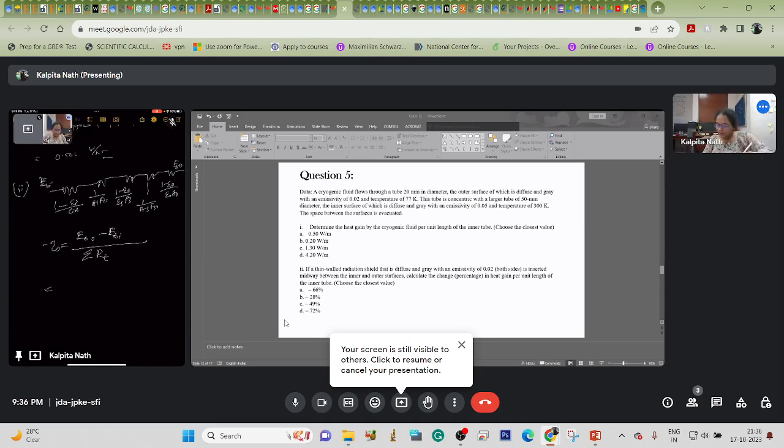And this is 457. We already know about this part, E_b0 minus E_bi; we already found this out earlier. So this upon 121 plus 121, which is for the first part. For the second part we don't know, so we will write 35 times 10 to the power minus 3 times 1, plus for the third part also 1 minus 0.02 upon 0.02 for the shield.